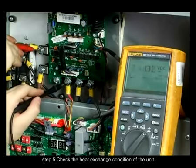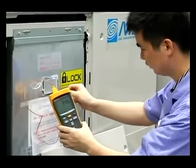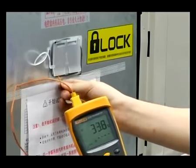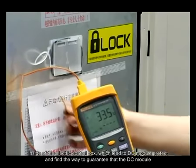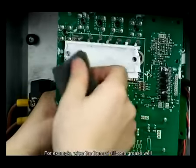Step 5. Check the heat exchange condition of the unit. Bad heat exchange will lead to high temperature inside the electronic control box, which can lead to DC module protection. If bad heat exchange exists, you must improve the heat exchange condition and find a way to guarantee that the DC module can work in the normal temperature range. For example, wipe the thermal silicone grease well.